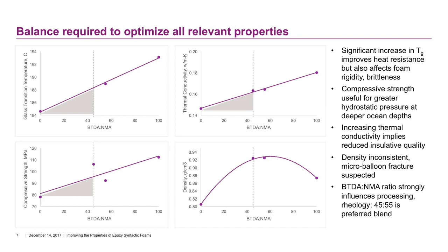The only drawback is that now the foam composite has become more rigid. You've introduced brittleness. So the full benefit of the BTDA in all likelihood needs to be pulled back to a reasonable compromise so that you've got a material with some good integrity and also gives you good heat resistance.